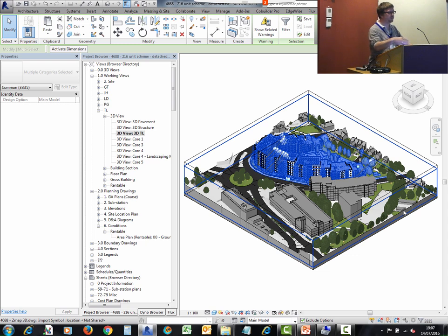Even before we developed this way of working with model groups, we would do things like electrical layouts, and you'd have wall hosted electrical layouts, and you want to be able to replicate those up through floors, and instantly you start getting problems where it loses stuff because it's not hosted, even if you're just copying and pasting from one flat to another, which is where we first started realising that I don't like hosted families. So I make the families just not hosted then? Yeah, I tend to create most of my content from scratch anyway, just because I like doing it.